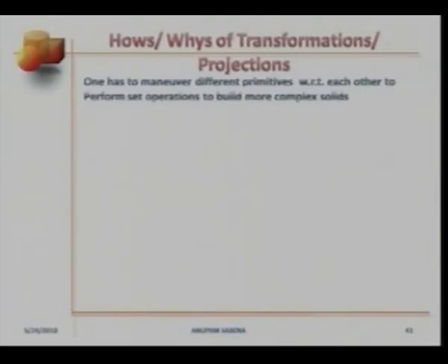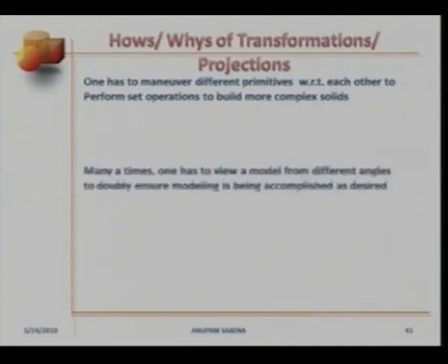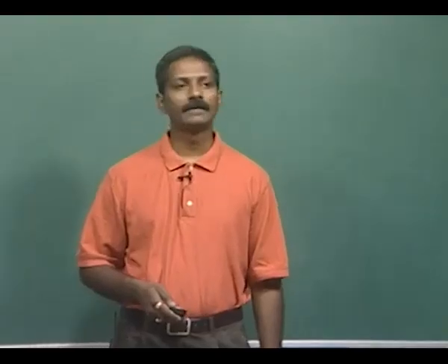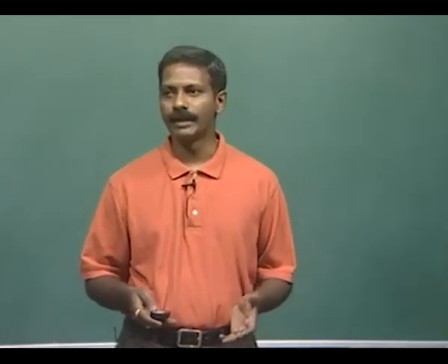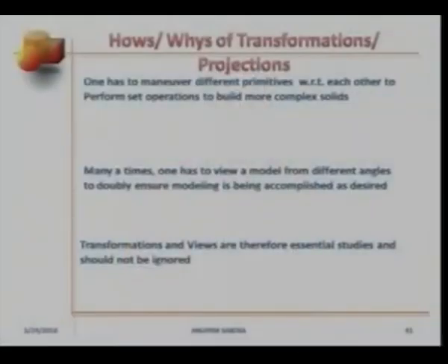Again, why would transformations and projections be important for us to study? One has to maneuver different primitives with respect to each other to perform set operations, for example, in constructive solid geometry, to build more complex solids. Many a times one has to view a solid model from different angles, from different views, to doubly ensure that modeling is being accomplished as you desire. Transformations and projections, therefore, in my opinion, are essential and they should not be ignored.